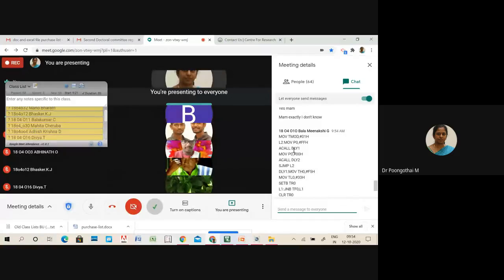So first you have to calculate the initial value of the timer for on time. So 65536 minus on time, where on time is 3 millisecond: 3 millisecond divided by 1.085 microsecond. What is the answer for 3 millisecond? 62771, I think so, approximately. Hexadecimal value?